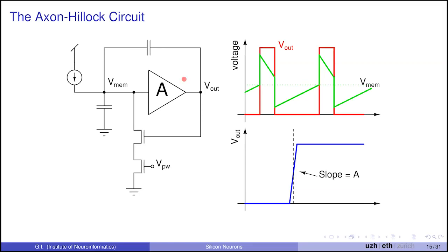So if you get close to the spiking threshold of the amplifier and you have noise, when you are close enough, you will have the amplifier switching up and down with the noise. So you would start to produce bursts of spikes that are actually correlated to the noise and not individual spikes with a frequency that is proportional to the input. So you have to have a positive feedback mechanism that actually kicks you away from the threshold, from this high gain region of the amplifier, such that you're above this noise margin.